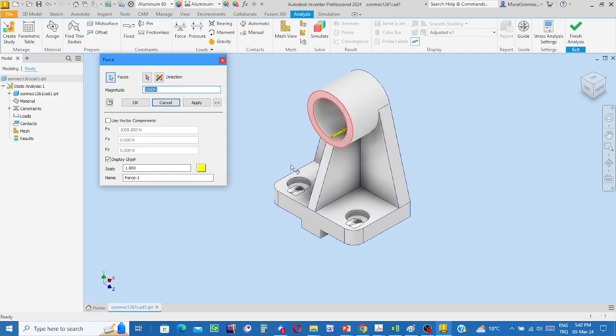Although there is only one arrow, be aware it is to show the sense of the applied forces. It is a representative vector. This does not mean that there is only one point force applied onto the surface. No, the force distribution is uniform over this annular surface. If the surface is an oblique or inclined surface, then select this box with a click and write the X, Y, Z Cartesian components of the oblique force system.